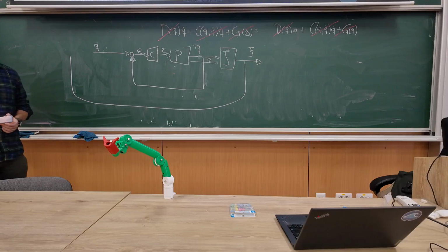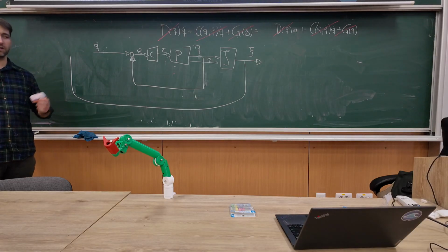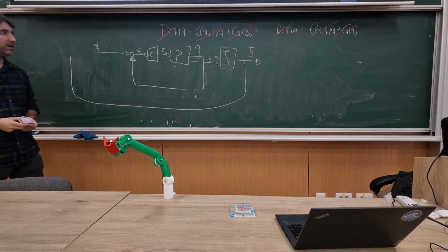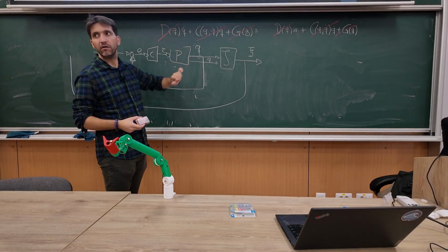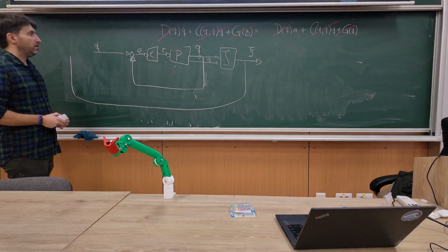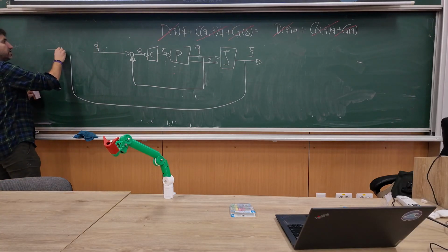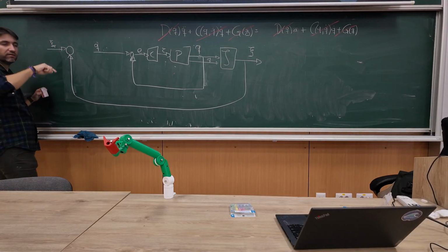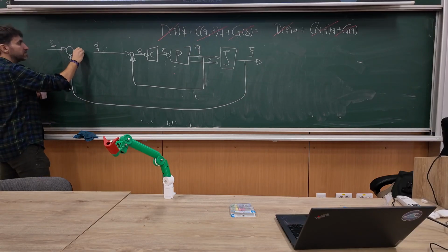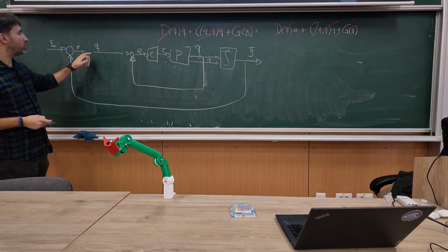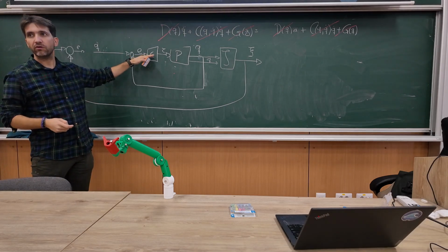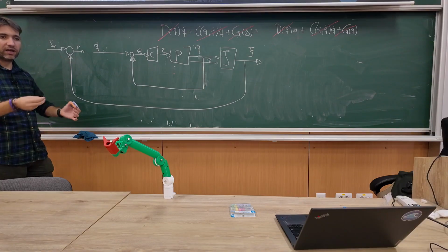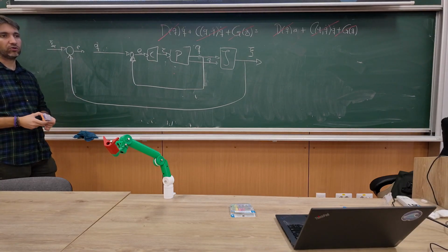But using the end effector properties for feedback is always tricky. The same thing with the position, right? It's something I cannot measure directly. I can only measure it indirectly. Then, okay, I have a reference Xi, the end effector velocity, and I calculate some error. I still have to decompose this error if I feed it to the controller to joint torques, right? So I have to go back down to joint torques.